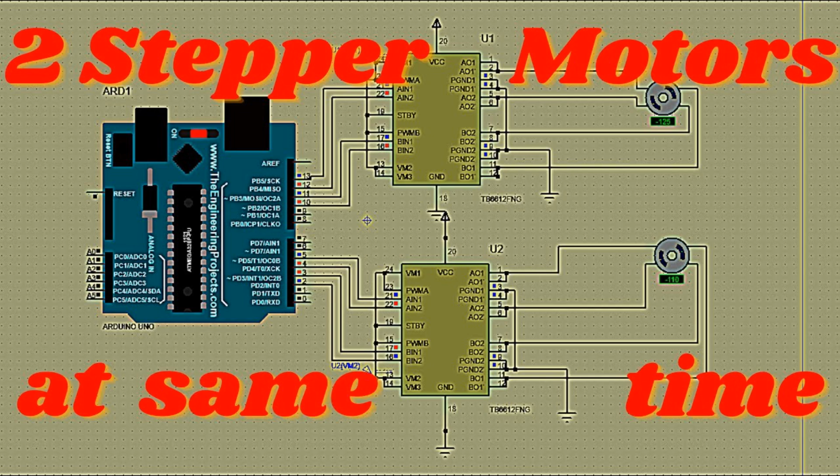1. Function of universal motor drivers. Universal motor drivers are designed to control the speed, direction, and operation of universal motors. They typically handle the following tasks. Speed control. Universal motors have a linear relationship between the applied voltage and speed. By varying the input voltage or pulse width modulation, PWM, signals, the driver can adjust the motor's speed. Direction control. By reversing the polarity of the DC voltage applied to the motor, the direction of rotation can be changed.